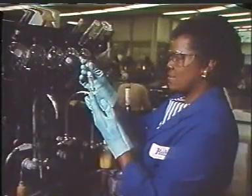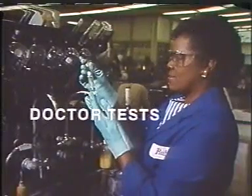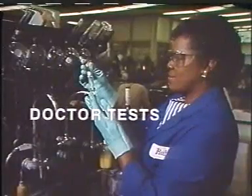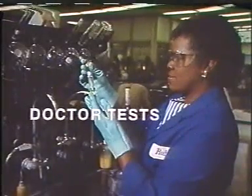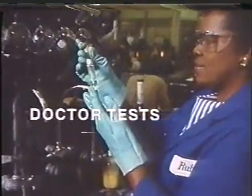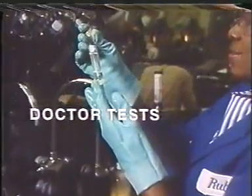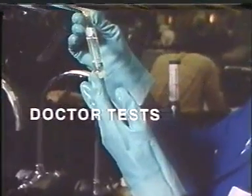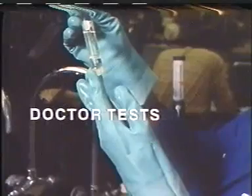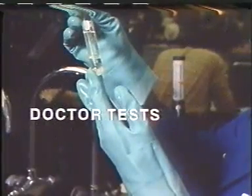The reformer feed is often given a doctor test to check for sulfur. In the doctor test, a sample of the feed is mixed with a chemical that reacts with sulfur. If the sample turns black, this is an indication of sulfur. It is important to detect sulfur in the feed because it can quickly deactivate the reforming catalyst.